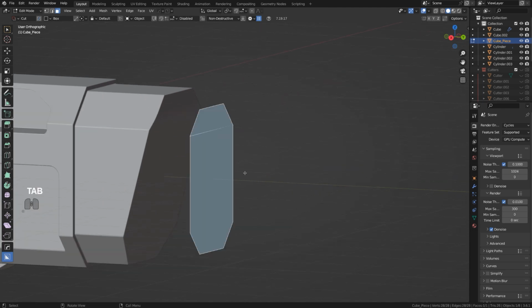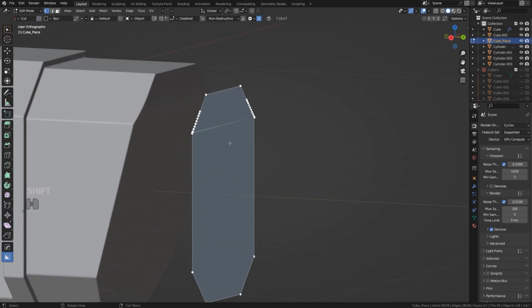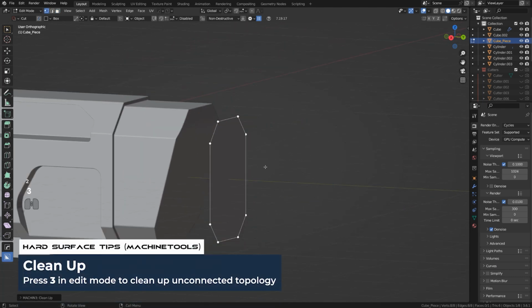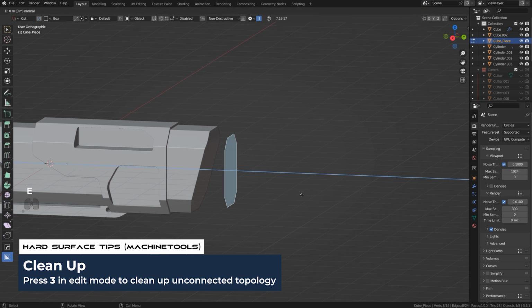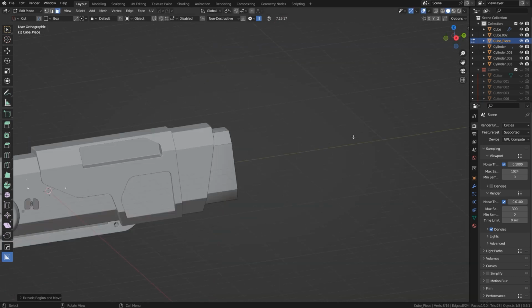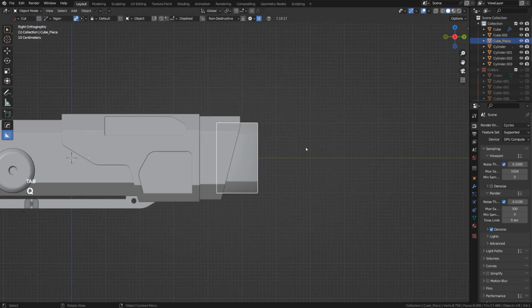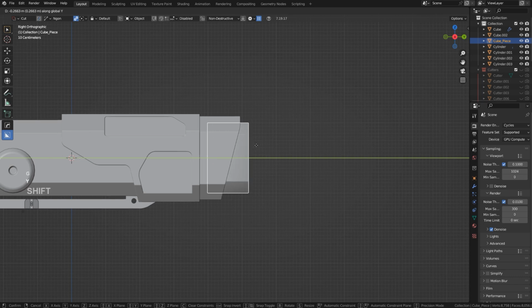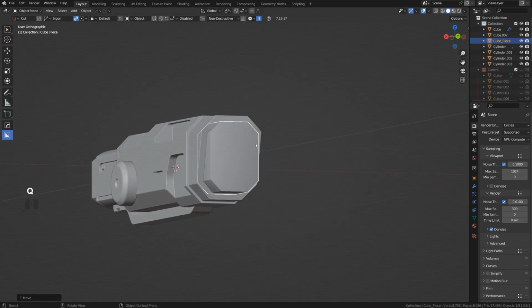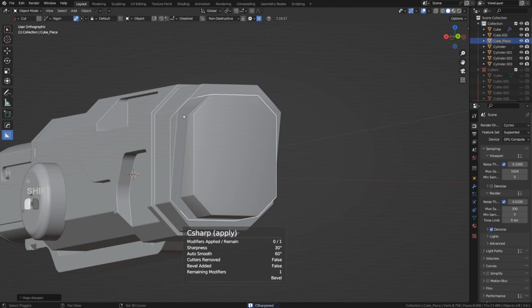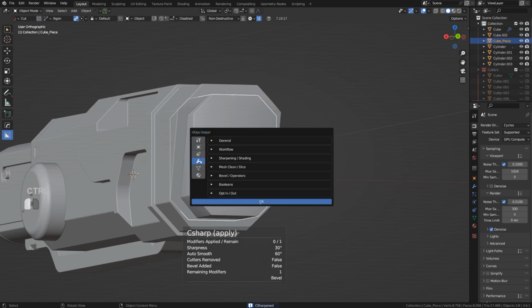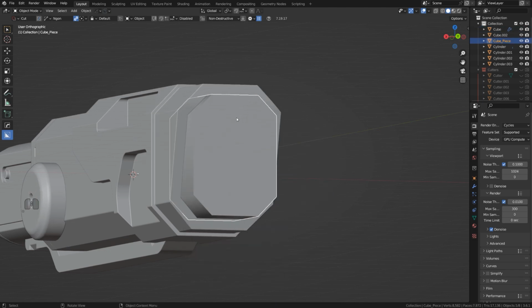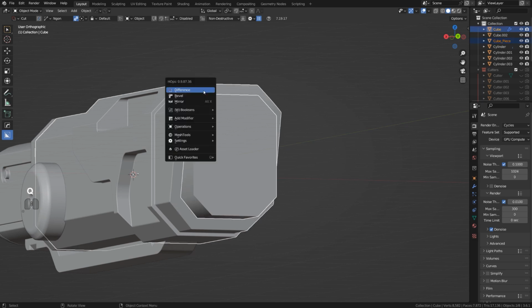faces, and then grab that. And we got some stuff here we need to fix, so press 3 to fix it, and then E and extrude it, right? And we got the scope here and the ending, so we can sharpen this, and we need to remove the bevel. You don't want to have bevels running on booleans. Select that, and you know, difference.